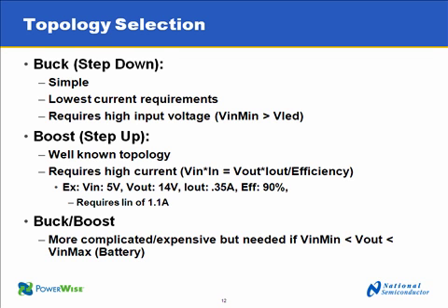A buck boost is something that can handle where your output is in between your input range. So if you've got, let's say, 10 to 20 in and 15 volts on your output, you can use a buck boost, but they tend to be a little more complicated and expensive, and so that's another option.